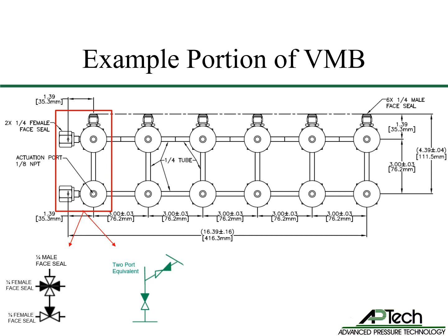The 3-ported pneumatic 3540, located at the bottom, has a 1/4 inch female face seal inlet port at 9 o'clock and a tube stub at 3 o'clock. This valve's outlet port at 12 o'clock flows to the 4-ported pneumatic valve. Located at the top of the red square, this 4-ported pneumatic valve's process gas enters the valve's inlet at 6 o'clock and flows through the valve under the seat to the 1/4 inch male face seal fitting.